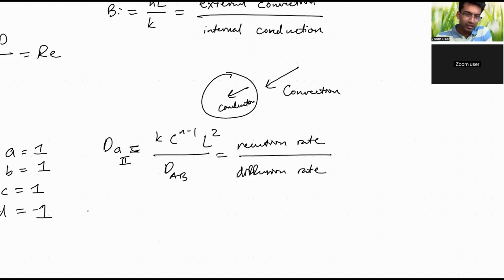And so hopefully now that we've gone to the end of this, you can see the value of having dimensionless numbers and actually going through the practice of deriving these through the Buckingham Pi, and how we can use these to scale from a smaller system to a larger system using just very simple values that we know.